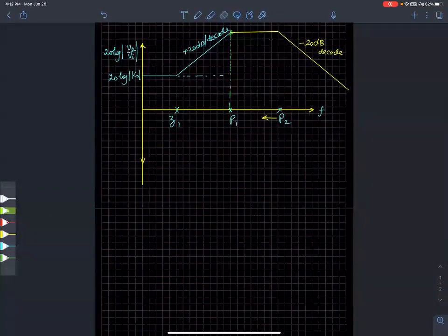On the other hand, if this pole were sitting right on top of the first pole, then you would see a negative 20 dB per decade roll off, plus another 20 dB per decade. So the roll off is going to be much steeper. Everybody with me?